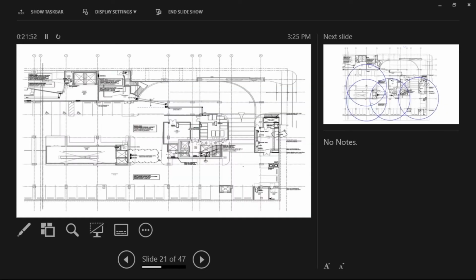So here's an example of an underground parking garage. And remember I mentioned the light bulb and the 360 degrees of coverage? I see a lot of plans and drawings come across my desk where the engineers place sensors on the perimeter walls. And just like a light bulb, if you have that light bulb installed in the ceiling, you have 360 degrees of light. But if you put that same light bulb in a wall sconce on the wall, you now only have 180 degrees of light. So you've wasted a possible 180 that you could have had.